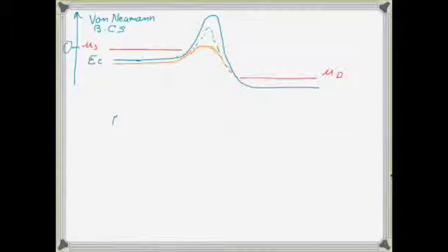The conduction band in the source falls. And remember, the Fermi level is always fixed at 0. On a very fine scale, you will see that the conduction band out here rises a little bit simultaneously. Again, mu d is fixed as just mu s minus q vdd.